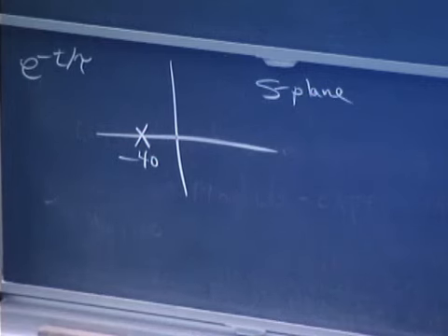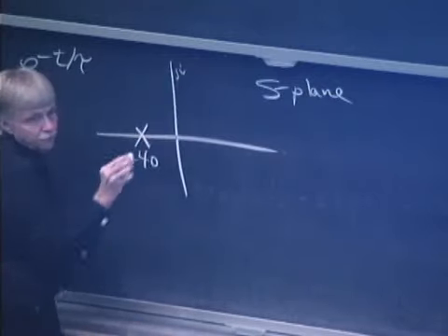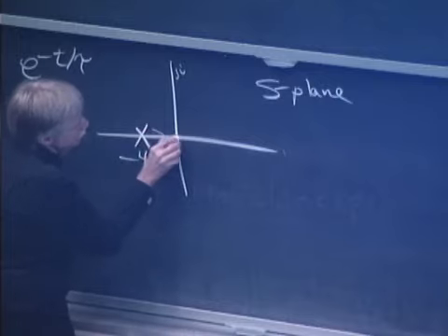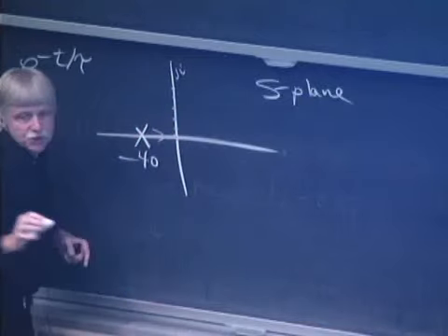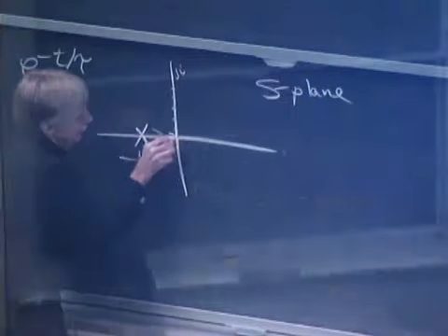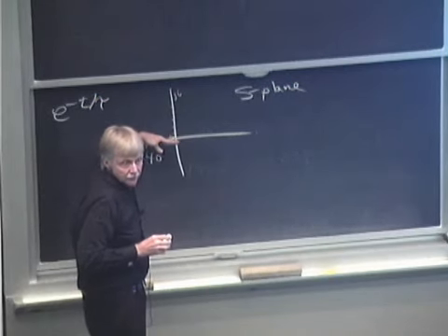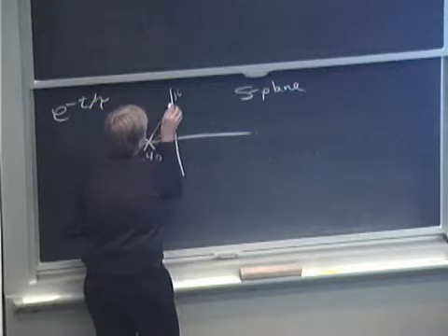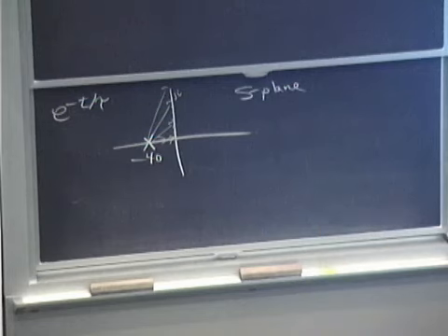How do you know that? Well, that's that Bode stuff we talked about last time. So if the pole were here, you would think about a vector. This is the j omega axis, right? You would think about a vector connecting the pole to some location on the j omega axis. If the location is omega small, that vector is going to have some length like that, and an angle of 0. As frequency goes up, the vector gets longer, which means that the magnitude gets smaller because the pole's in the bottom.